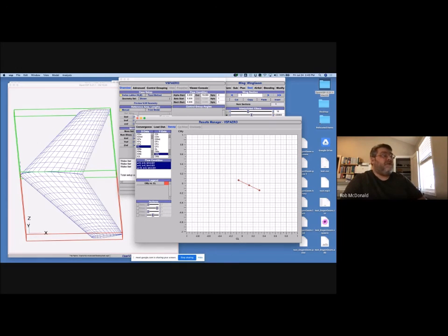And then there's the question of, do you want to fly at best range, or in your case, since the whole point is to get a sensor in the sky for a long period of time, you probably want to fly at best endurance. Or you may want to fly part of your mission. Let's say you want to patrol an area that's far away. Then you want to take off, fly best range speed to get to that area, and then once you're there, fly at your best endurance speed. So in that case, what I would say is